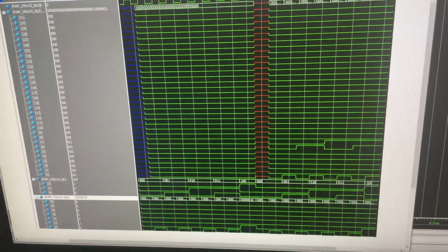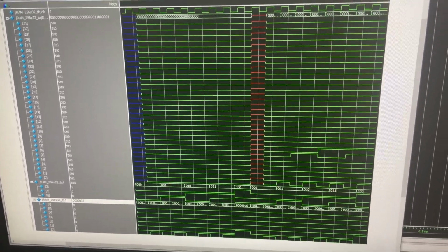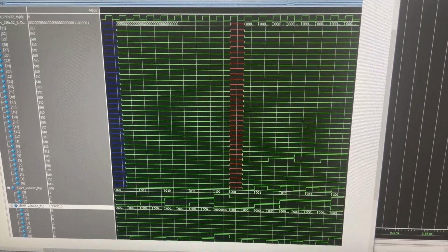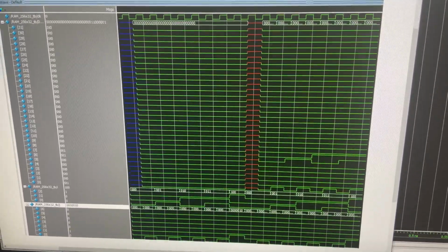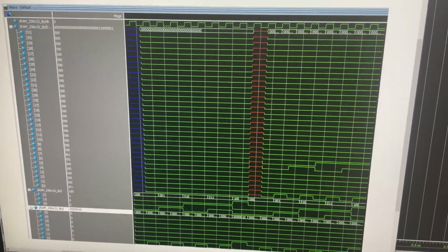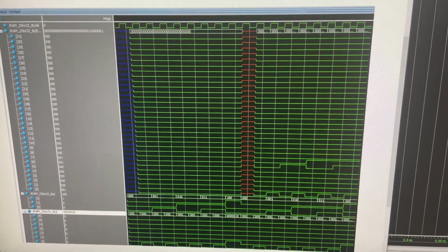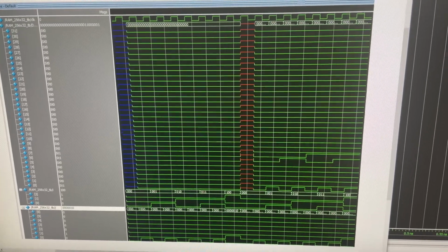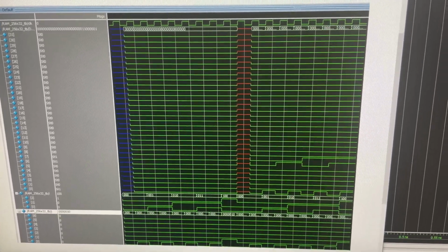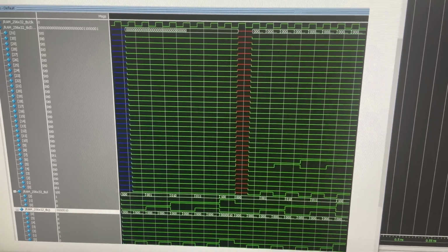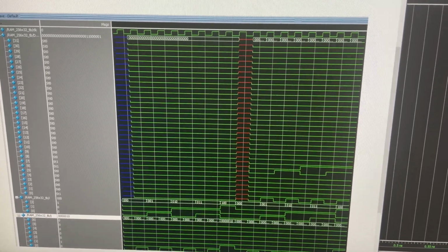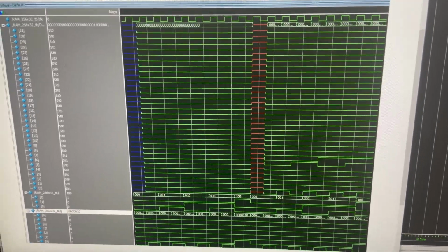If we look at the right side, which is the read portion, we are going to make the read write 0. Read write 0 outputs the value, as shown from the right side. Whichever of the addresses that we input values into can output the value that they hold in the test bench by using the tri-state buffer. The read function of the 256 by 32-bit RAM works well, as you can see.